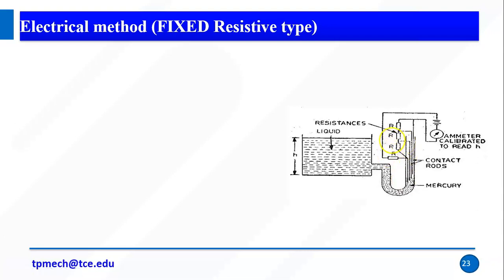Again, we have a series parallel of resistance rods. Assume that here we have 4 parallel rods. The first parallel from the bottom, assume that is R1, R2, R3, R4. Now assume that R1 is the lowest level, R2 is low level, R3 is medium level, R4 is high level. So over the rods we use resistors. So the resistors are connected in parallel with different height levels.